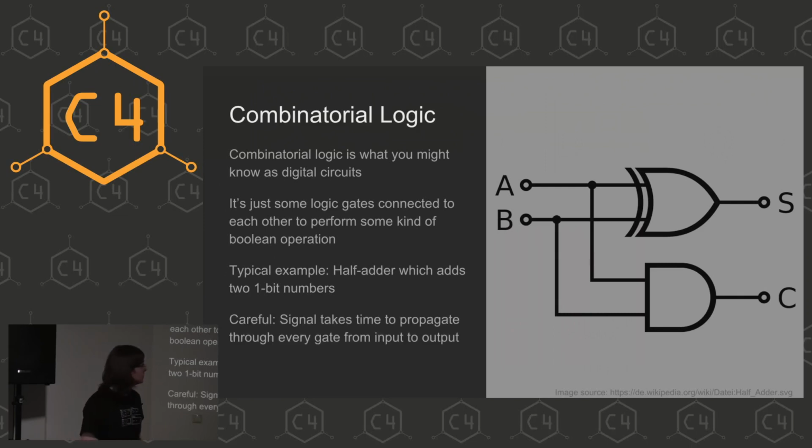And also here we need to be careful, because that signal that travels from the inputs to the outputs takes time, because all these gates need time to switch and settle. So it takes some time for the input values to travel through all these things to the output until the signal is stable on the output. That's called the propagation delay.